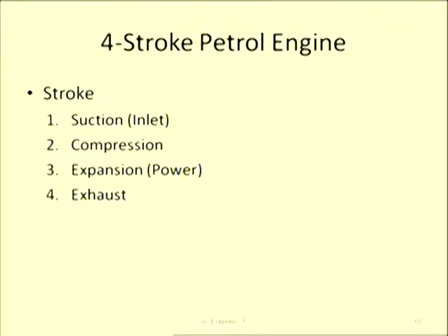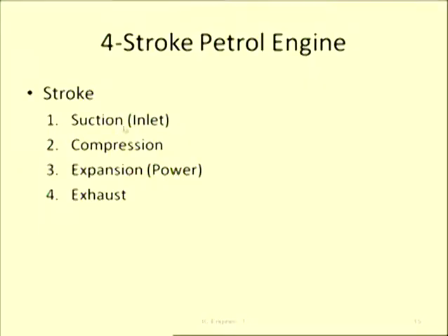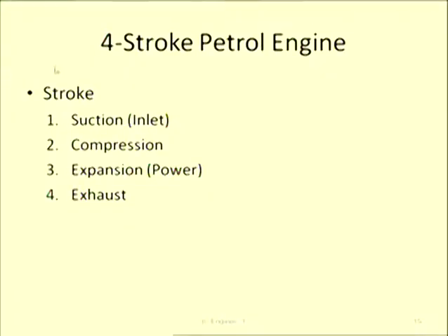So first we will discuss the 4-stroke engine. As I have already mentioned, but in a systematic way we will see now, the first stroke is the suction stroke. Suction stroke means suction or inlet will happen. So air and fuel mixture in case of petrol, and air in case of diesel, will get into the engine, that is called suction stroke. Next stroke is compression.